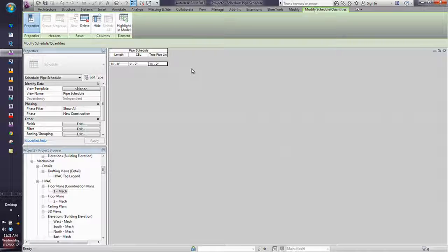Okay? Yeah. So going back to electrical panels. Whenever you circuit, whenever you connect equipment to equipment, it keeps the name. Let's say you name your panel this way, and you actually connect it to another panel. You'll see that it'll bring in that panel name. Well, once you actually connect devices, by default it brings in the load classification, and then you can actually rename that as well. But whenever you hit the reset names, then it goes back to load classification.